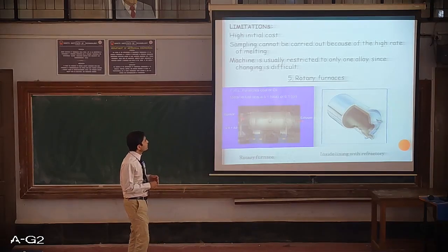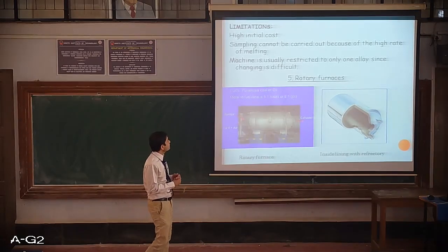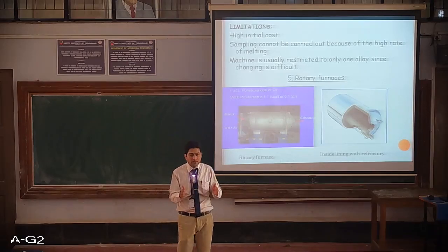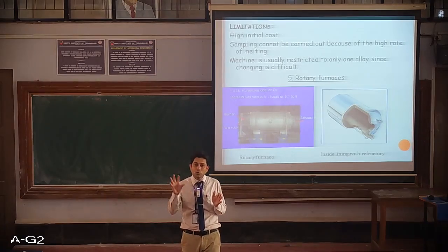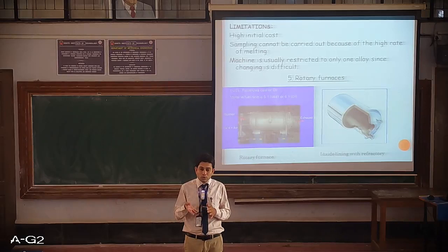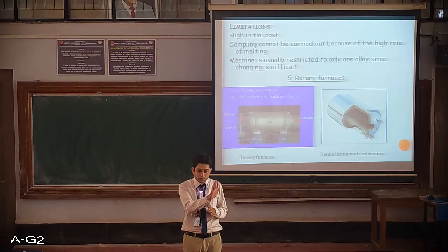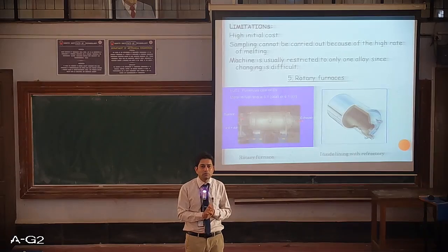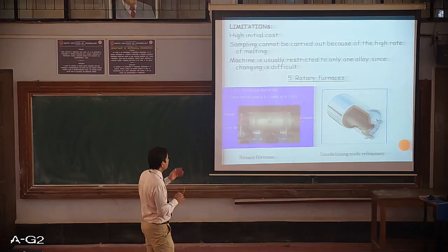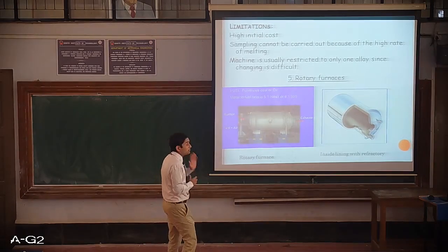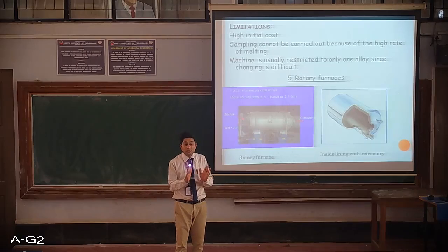And the machine is usually restricted to only one alloy since charge changing is difficult. So if you have an induction furnace, it will be dedicated only for one type of alloy. If you wish to change the alloy, again it is a slightly difficult affair. You need to clean the inner portion of that furnace and then do the changeover to the other alloy. So that is one more difficulty which is associated with this type of furnaces. So this completes your induction furnace which is there in your syllabus.